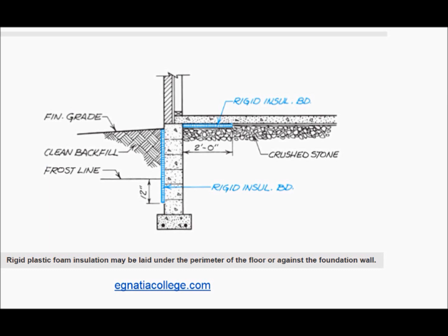Another technique often used to prevent groundwater from seeping through the foundation is coating the foundation wall with asphalt foundation coating. At this point, subsurface work outside the foundation wall is completed, but backfilling should not be done until the superstructure is framed. The weight and rigidity of the floor on the foundation wall help the wall to resist the pressure of the backfill. If the backfilling must be done before the framing, the foundation walls should be braced.